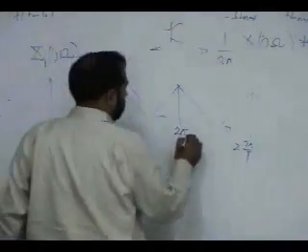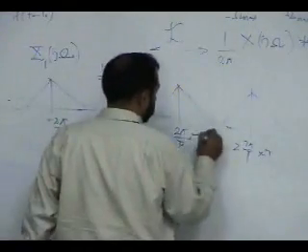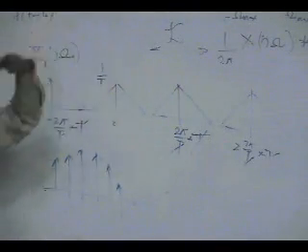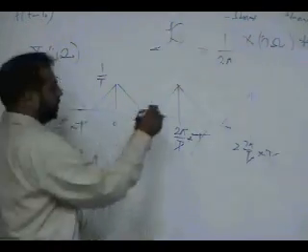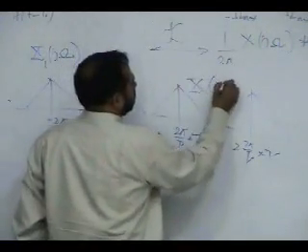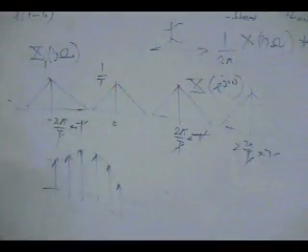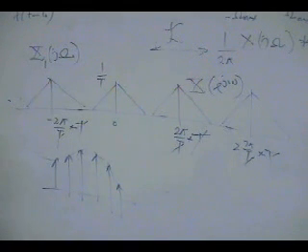So if you multiply by capital T, T cancels out with T, T cancels out with T. So that operation is equivalent to this operation in the frequency domain. Now this is a digital spectrum, which is X(e^jω), and we know that the Fourier transform is periodic over 2π. So you're getting a perfect mathematical relationship.